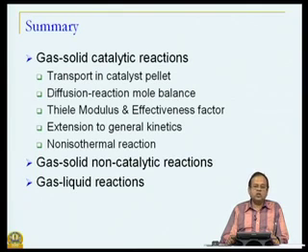This idea comes from the fact that in the absence of reaction there still can be mass transfer, which would be a simple absorption process depending on the saturation concentration of the gas in the liquid. So, we would have got this rate without any reaction, the rate of absorption.